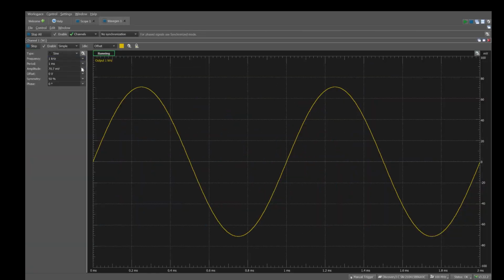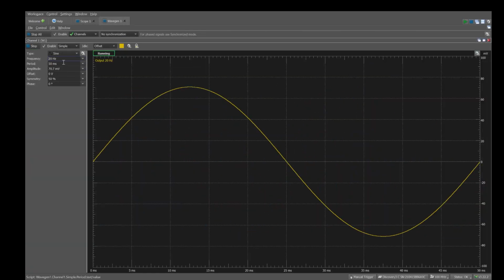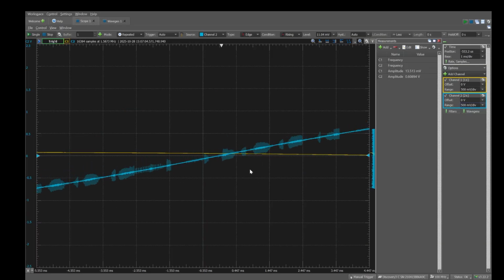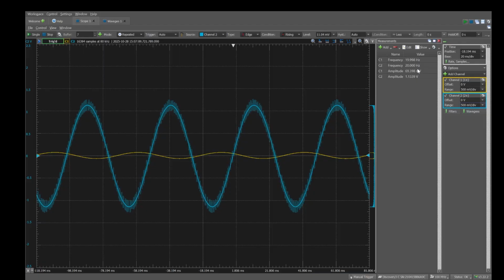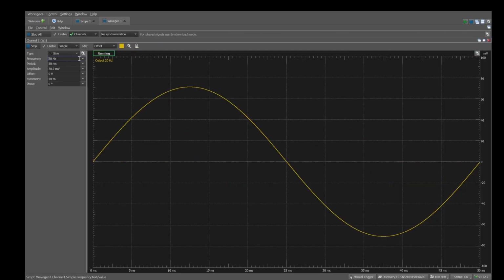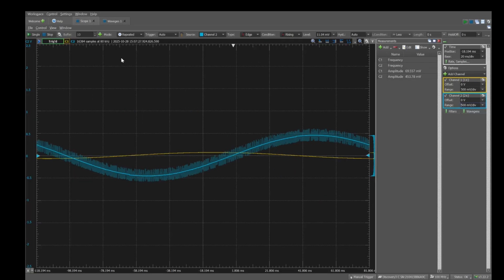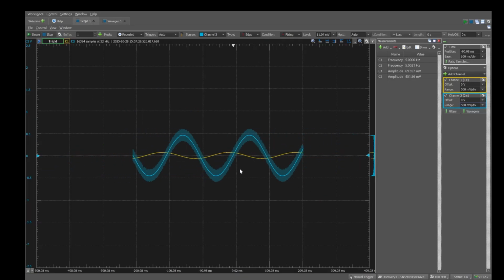So now we're going to check 20 hertz. All right, we've changed it to 20 hertz. And we can see we get a little bit of a decrease there. So it was 1.4, now we get 1.1, 1.13-ish. So that's good. We have a little bit of a drop, but it's not significant. So now let's drop even farther down to 5 hertz. Come into 5 hertz, significantly dropped. So we've attenuated the signal way more than we were before.